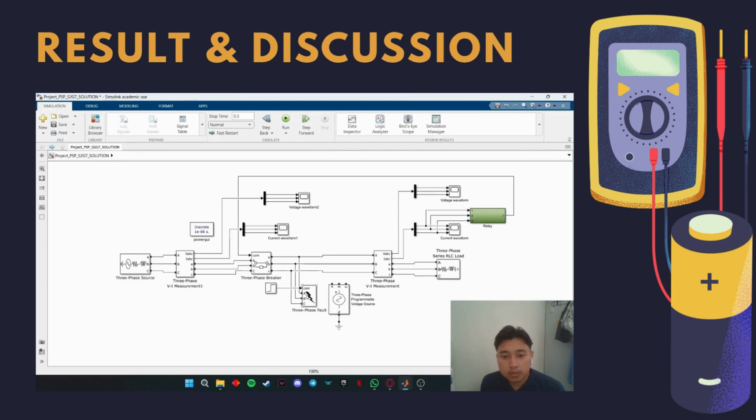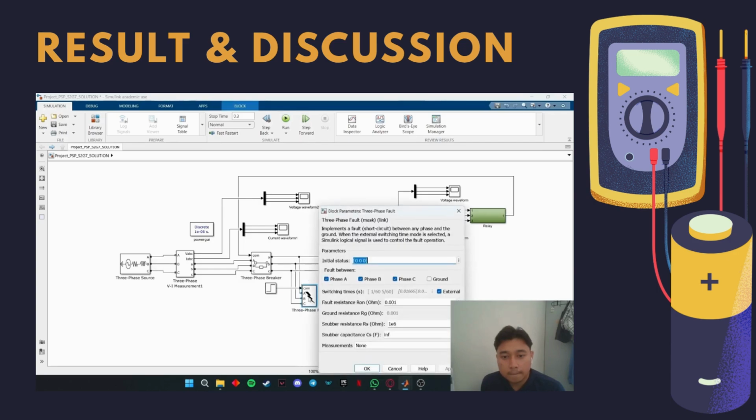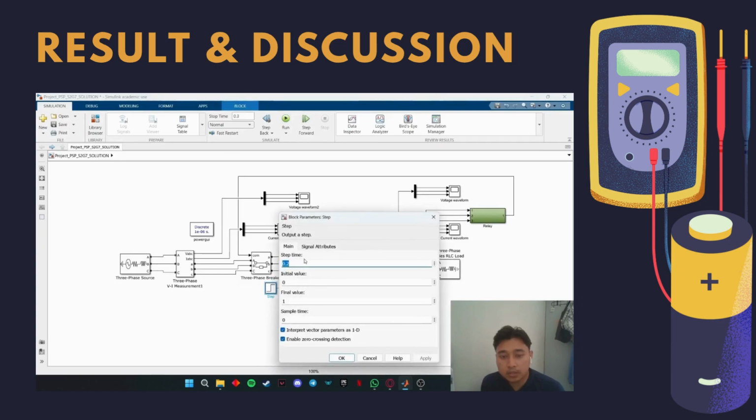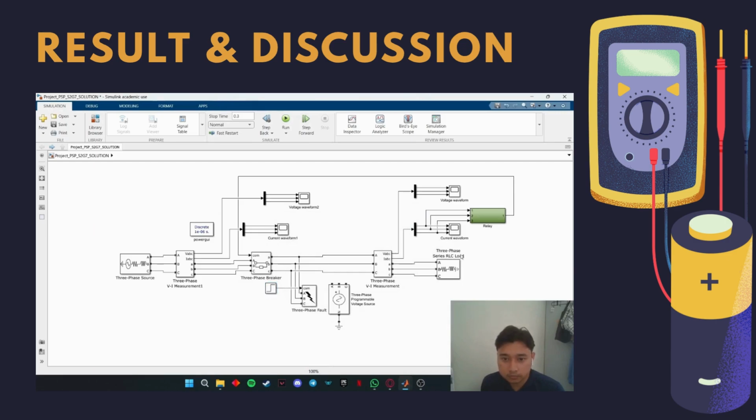So the three-phase fault we also put at the balanced three-phase, which is for each phase. We also set up the step here, where we need to inject the fault at 0.2 seconds, and we need to run the simulation to see the voltage and the current waveform after we put the three-phase breaker and the relay.